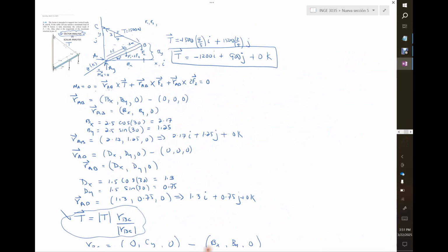So basically this is the story. The sum of all the forces in the X direction, going positive in that one, equals 0. AX is positive, then the only force that will cancel out with this AX is the tension force going that direction, and we got that value. That value is coming from here, minus 1200, equals 0. Easy. AX is just 1200 Newton.